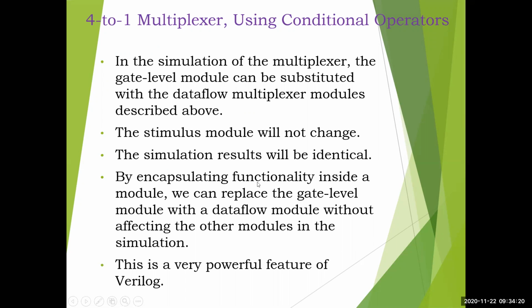Okay, by encapsulating functionality inside a module, we can replace the gate level module with a data flow module without affecting the other modules in the simulation. See here, this is the beauty of Verilog HDL. We have just changed how we describe things. The remaining IO ports, all these things were changed, right? We have just changed the name for the sake of it, or you can keep the same name and replace it with the data flow module without changing the internals, right? So this is a very powerful feature of Verilog.